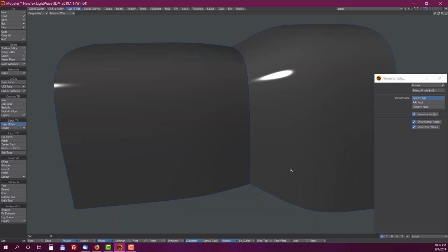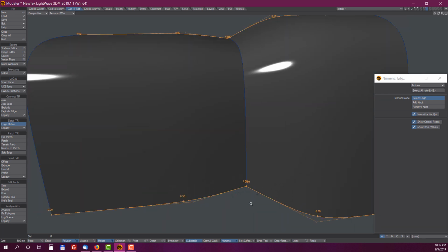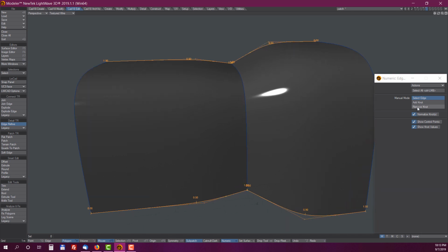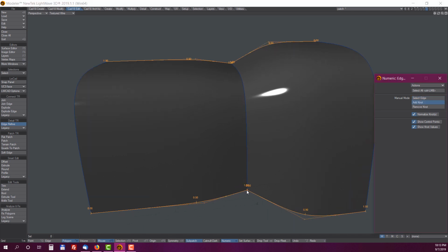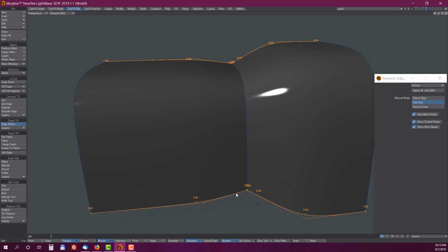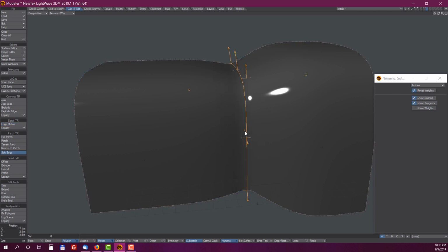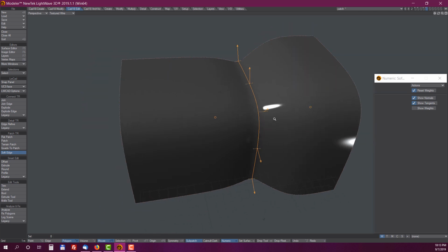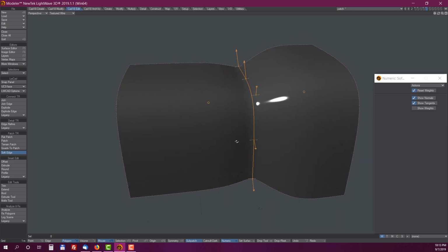So let's say I select these two edges here, and you add a knot and change the level of detail around this edge, so let's say one knot here, one knot here, and now when you apply soft edge, the softening part is much smaller. So this way you can change how this tool will create the softening area, together with the Edge Refine tool.